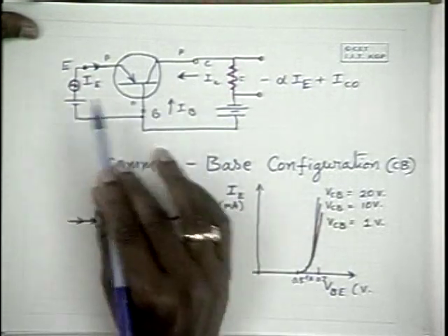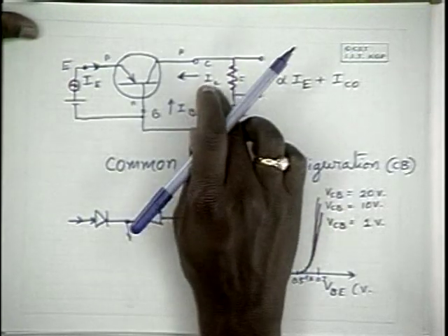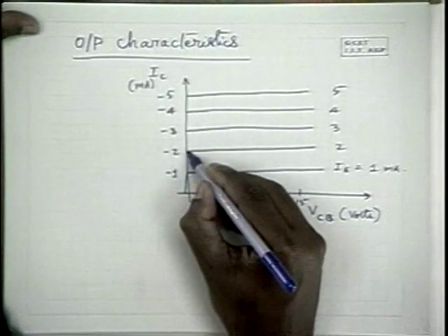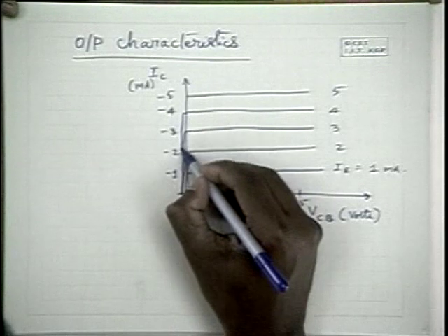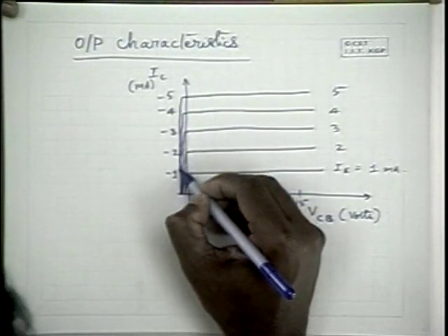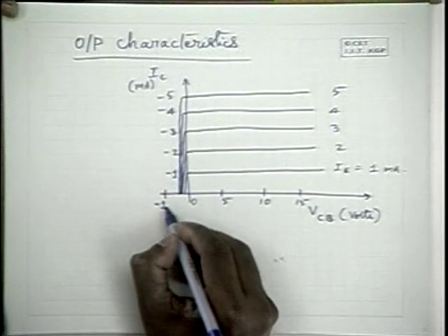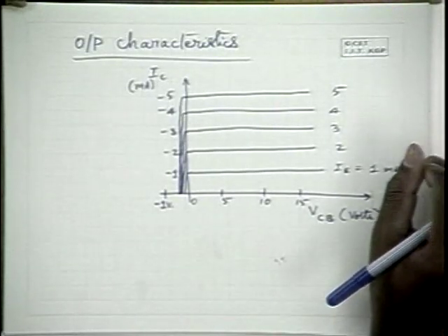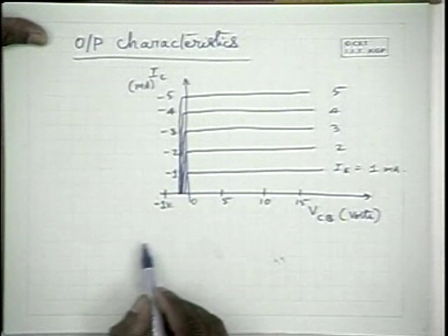So IC equal to alpha IE minus alpha I is no longer valid. In fact, IC now becomes positive from negative. Therefore, the characteristic IC drops very rapidly with a small amount of positive potential. So if this is minus 1 volt, within a few tens of millivolts the collector current drops because of the disappearance of the potential gradient. And if you further increase, IC becomes positive.